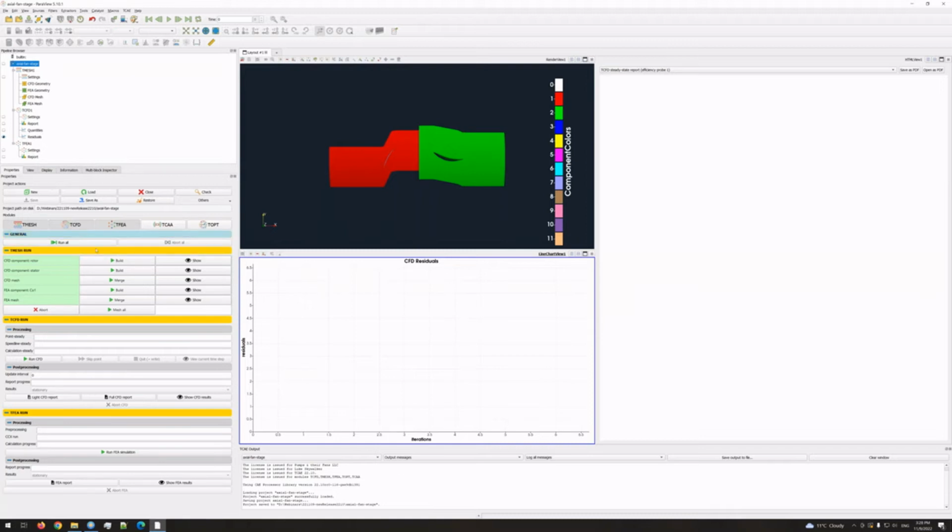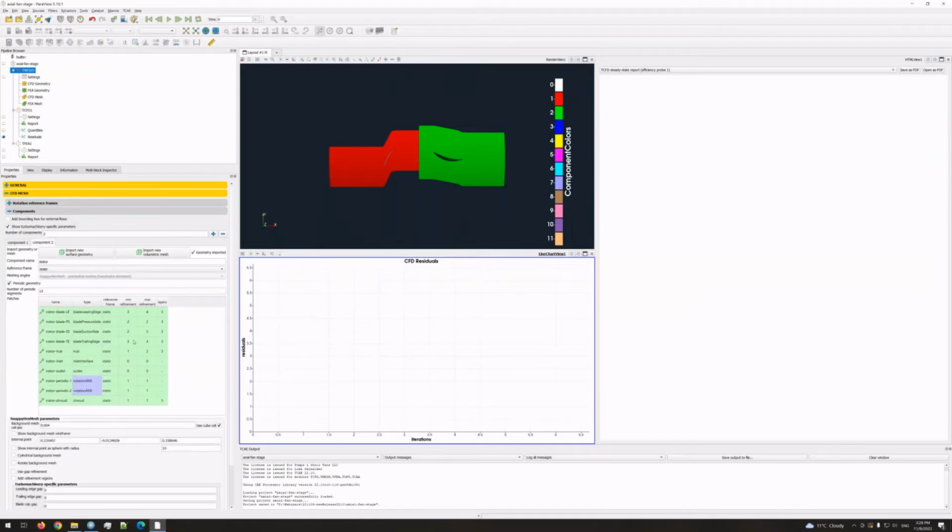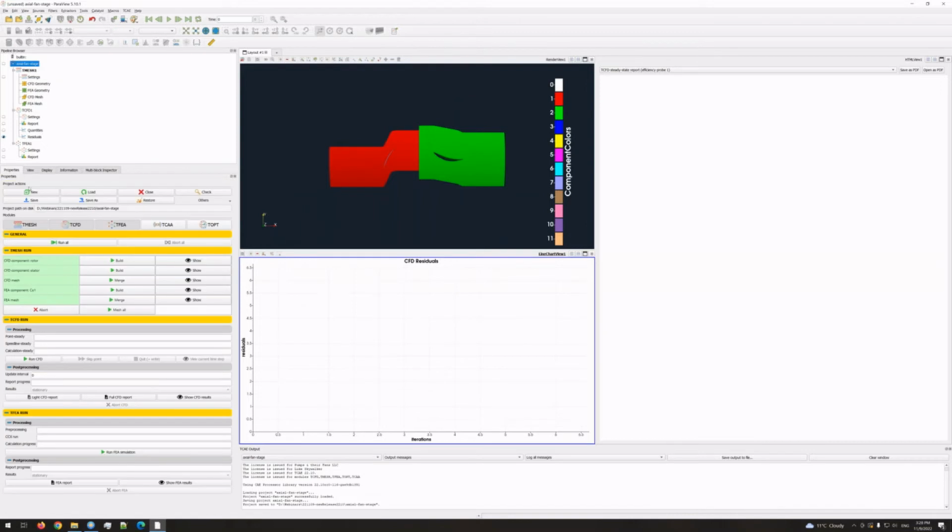There is no need to run the case, because for this project I have already generated the mesh. But as an example, if I change some parameter in, let's say, the second component, for example, the suction side, I will increase the maximum level of refinement. Then I go for the save. You can directly see what part of the meshes needs to be regenerated, and I can hit the run all button, and it automatically generates only the mesh which needs to be generated with respect to the changes that I made. So this new project management is always checking for the actual state and for the new setup, and it will always manage what is needed to be run, rather than rebuilding the whole simulation again.